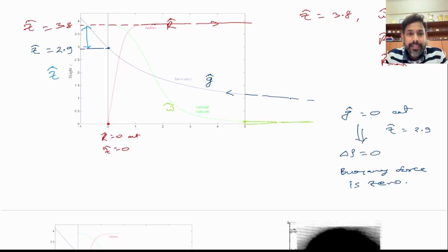because the maximum height it reaches is 3.8, not 2.9, and that is happening because the plume still has some momentum flux. Even if the buoyancy flux becomes zero, the temperature difference, density difference, or concentration difference between the plume and the ambient becomes zero, it has gained this vertical velocity, right? And that vertical velocity is this value, right?